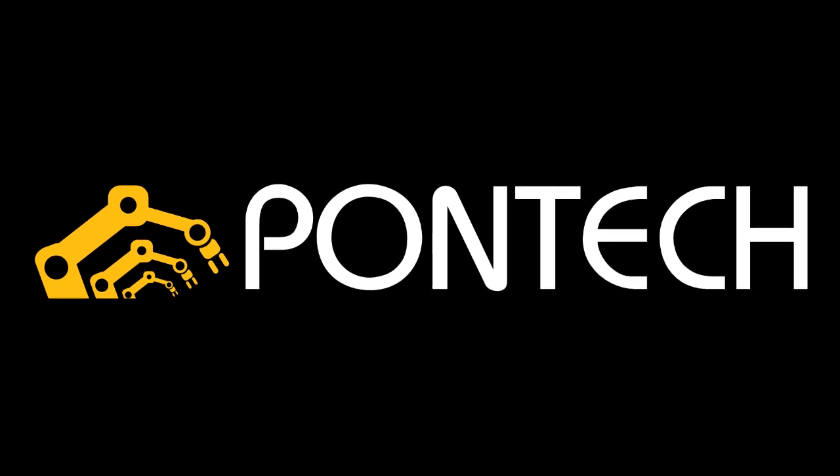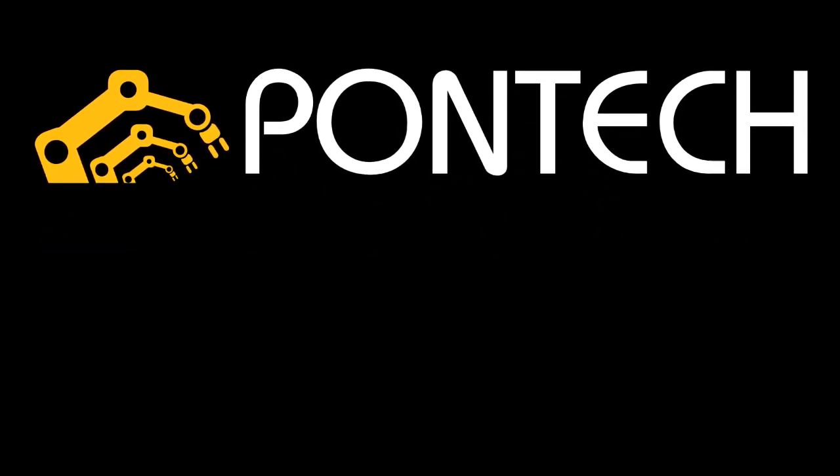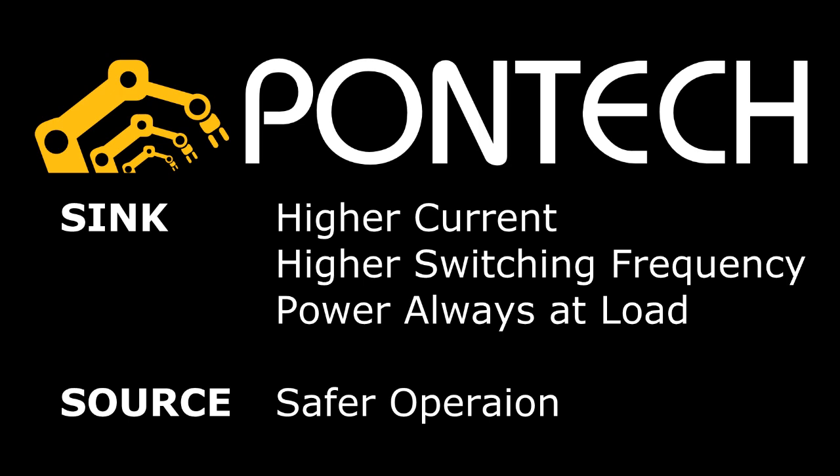So you might be asking yourself at this time, if both work equally well, why might you choose source over sink? The primary trade-off is between performance and safety. Transistors that drive sink tend to be able to handle higher currents and operate at slightly higher frequencies than source transistors. However, when a sink transistor is turned off, a short of your load to a surrounding housing that may be grounded will energize your load.